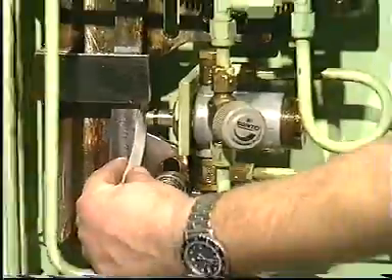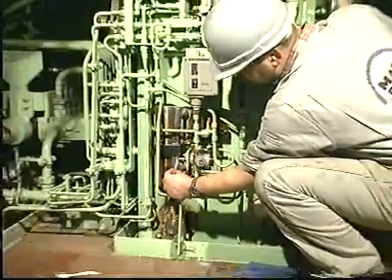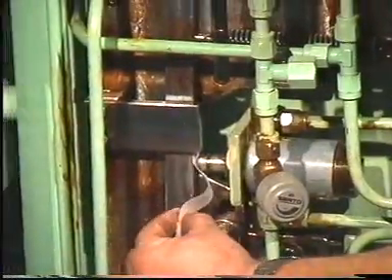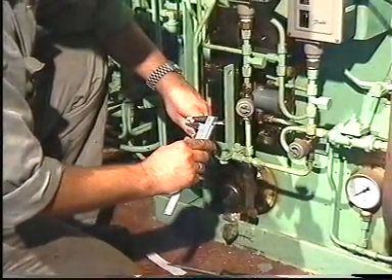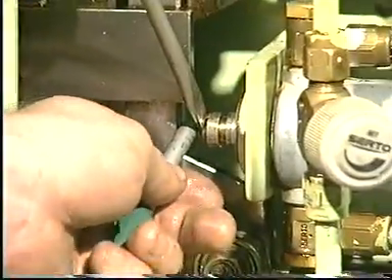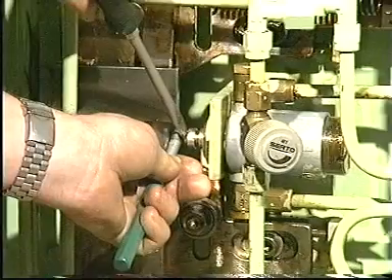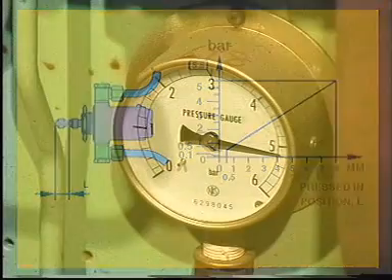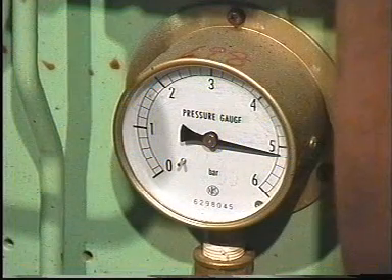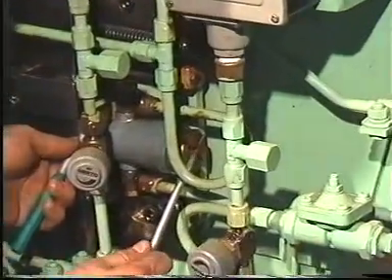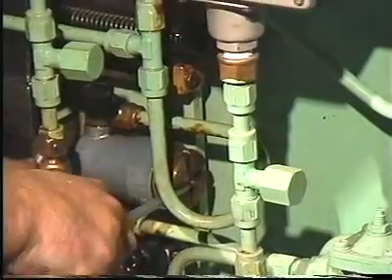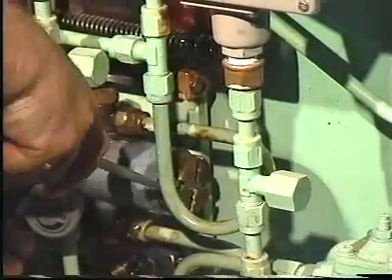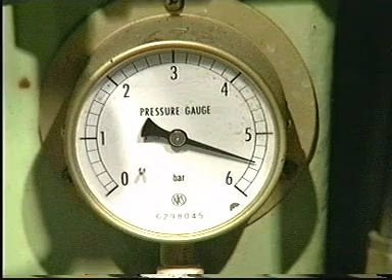Turn the regulating hand wheel so that the steel bar just touches the pilot valve. Insert a distance piece with a thickness of precisely 8 mm. If the control air pressure deviates from 5.5 bar, loosen the lock screw and turn the spring retainer cap of the pilot valve until the pressure, which can be read on the pressure gauge on the engine side control console, reads 5.5 bar. Note that it will not be possible to obtain the correct pressure if the throttle non-return valve is not fully open.